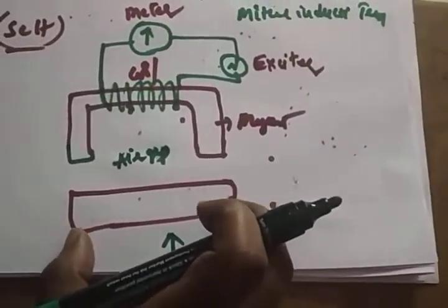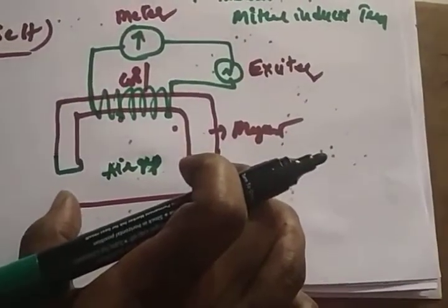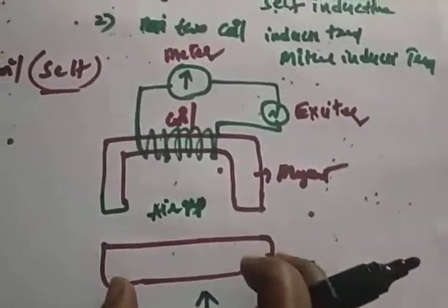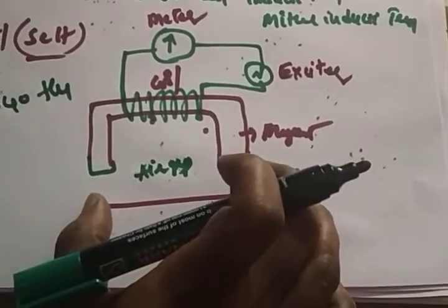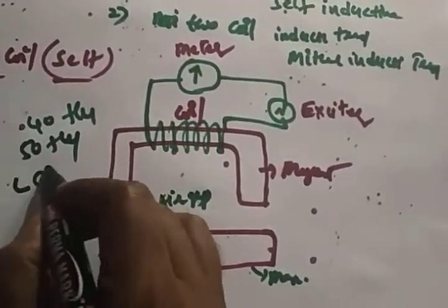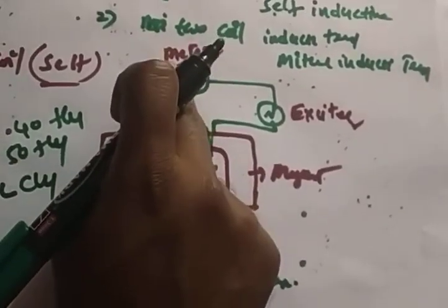But suppose the magnet is here now, and you move it like this. Suppose at this position you have a flux of 40, right? When you move this magnet upwards, what happened? The air gap will be changed, that means the change in flux is also generated now. So the flux is 50. That means you are changing the flux. If the change in flux happens, the inductance also changes. How much the inductance changes can be found out by the meter itself. Whatever the output of the meter is analogous to the motion that you applied.